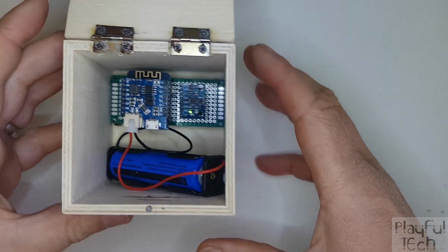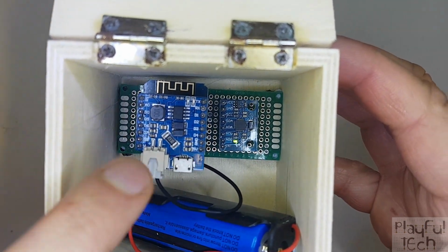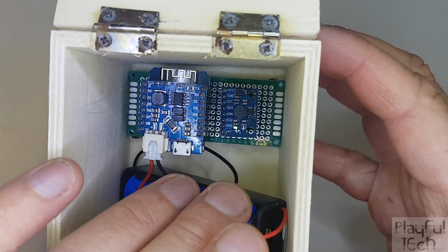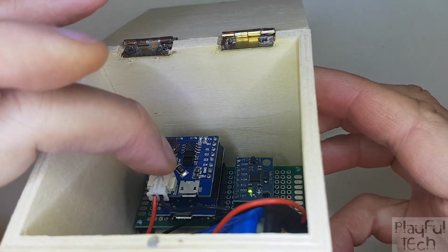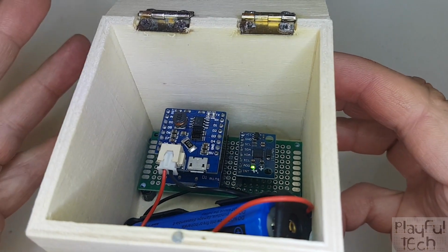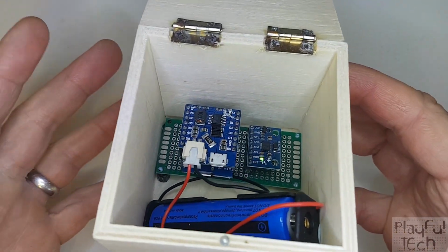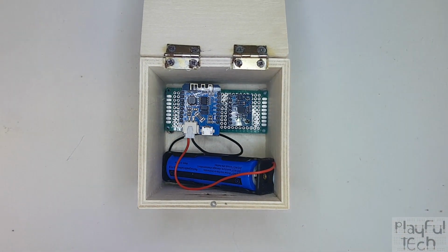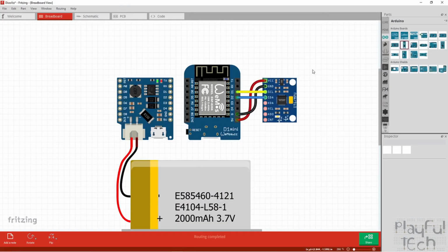The reason why I'm favouring the Wemos board particularly is because it comes with this battery shield here, and that means you can keep the LiPo battery connected to it, and it can charge through this USB port here. Obviously, when you've got any portable props, you need to give consideration to how you're actually going to power them and keep them charged. And this is a really convenient little shield that enables you to do that. So it's a bit hard to see the wiring inside those little boxes. So let me show you a diagram in Fritzing instead.